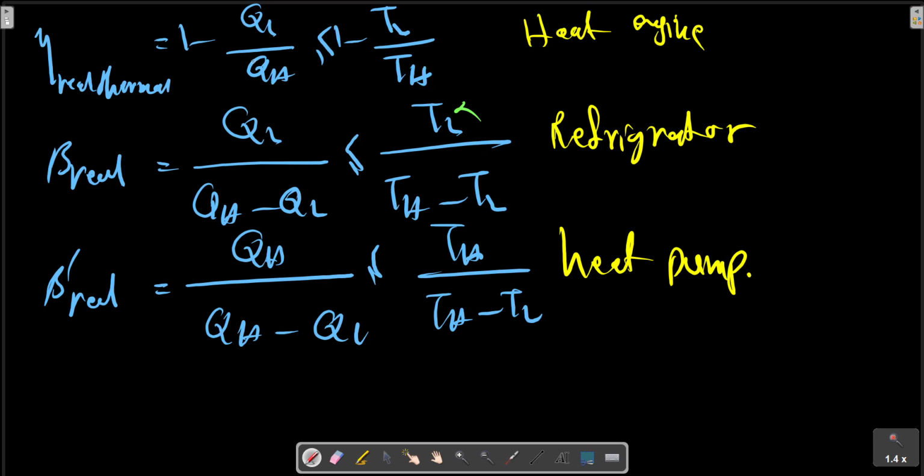Absolute zero represents the limiting temperature that can be achieved, and the amount of work required to produce a finite amount of refrigeration approaches infinity as the temperature at which refrigeration is provided approaches zero. This expression approaches zero, so we have infinity for the coefficient of performance, COP.